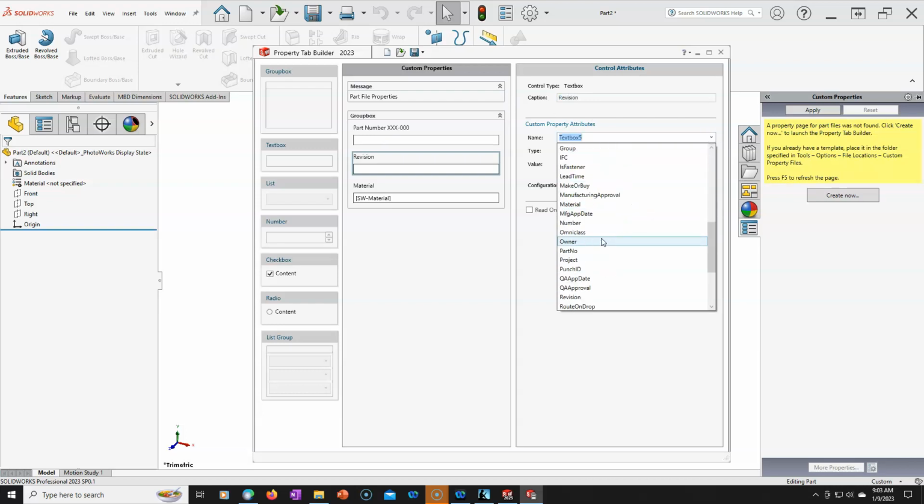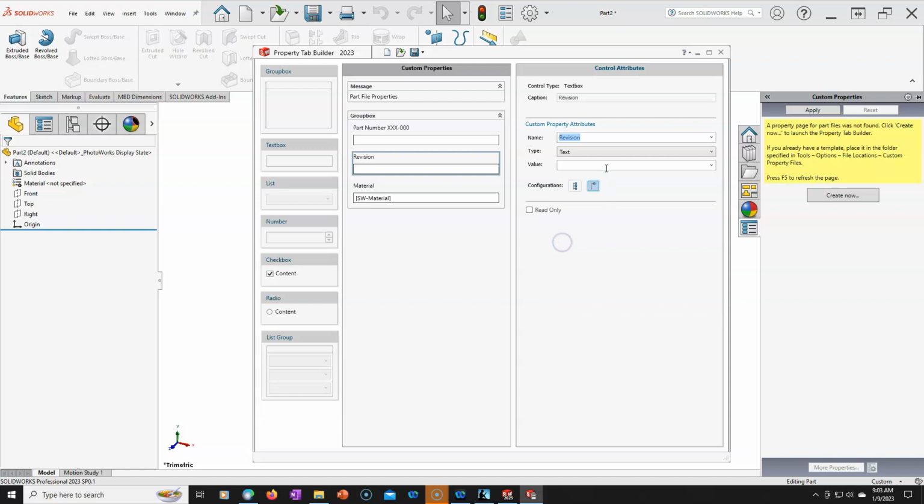and then we'll do the pull down, revision, and there isn't really a rev. So we'll go with the default, typically is going to be rev A. I've also done 0 for the default, until we get to a production release and go to A, then the 0 pops up that there still needs to be some approvals. For the whole file, maybe I'll make custom. All right, so it'll just be global for that file.